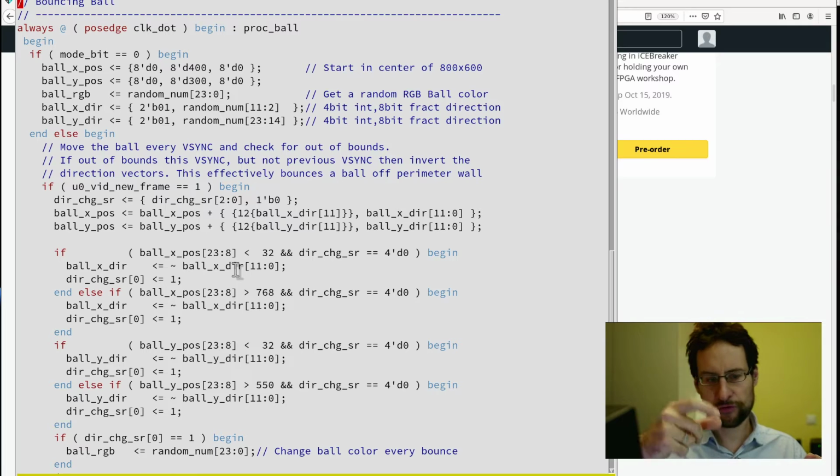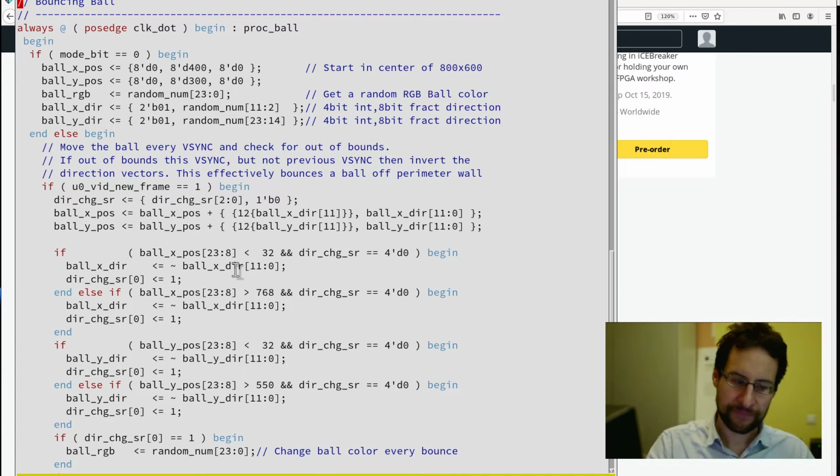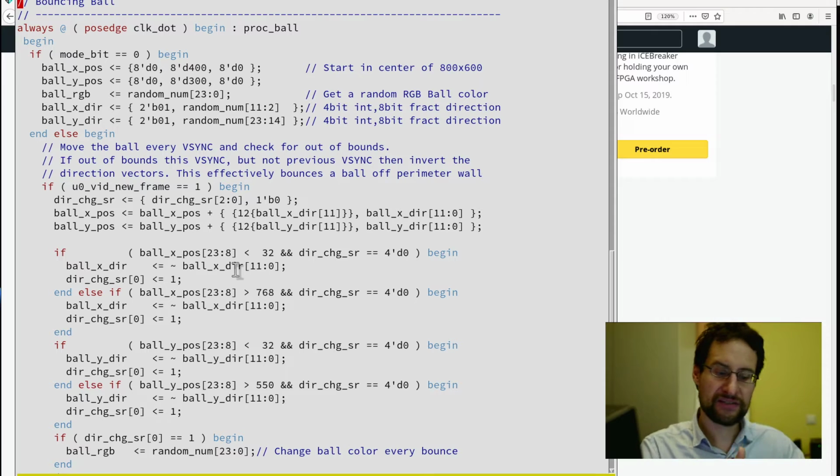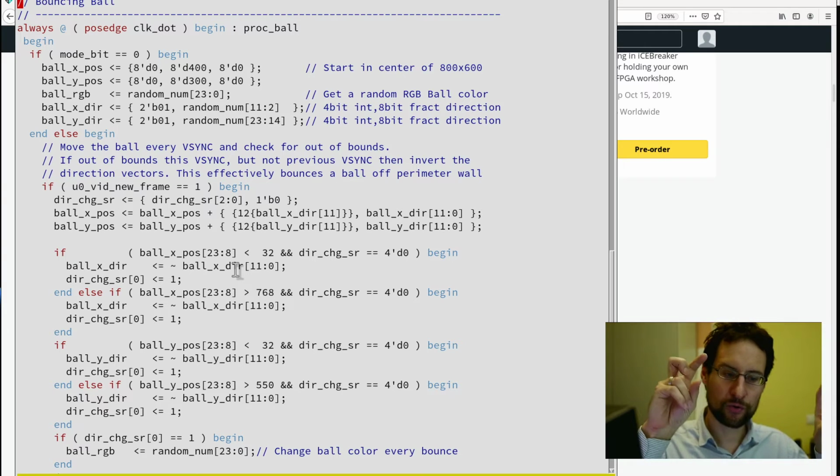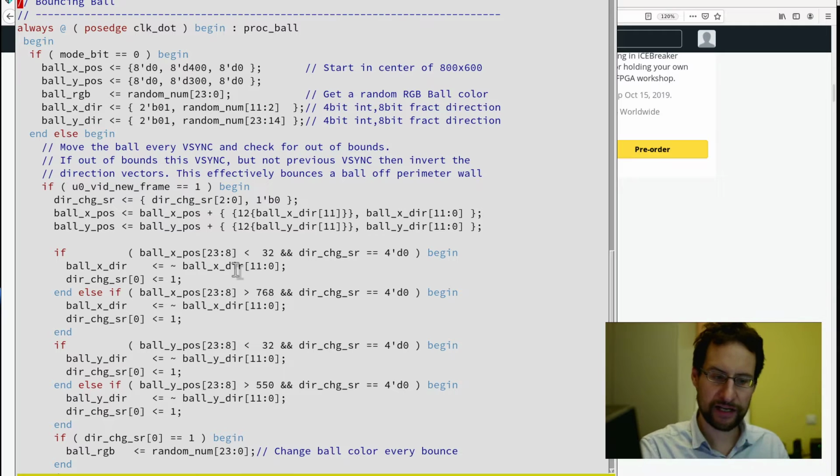The CPU could not even generate this test pattern so fast, especially this 12 to 40 megahertz CPU in real time. That is why on a 386 or Pentium, or even today's Core i7 and Core i9, you would draw this slowly in a video memory buffer and scan it out. This is why it's called scan lines or scan buffer. Scan this out on the video graphics array, and the FPGA can do it differently.